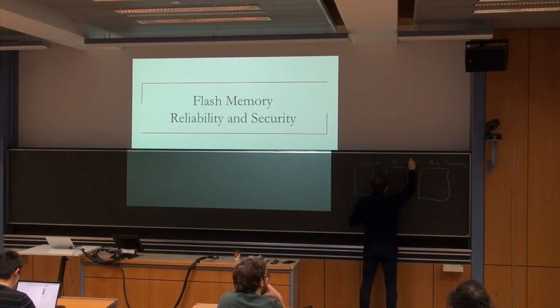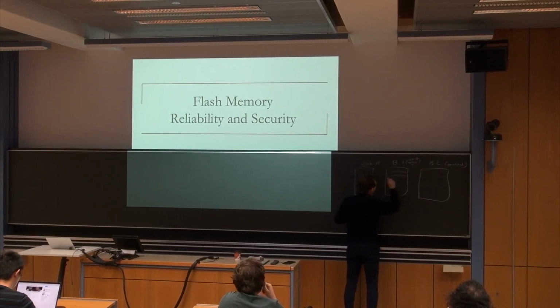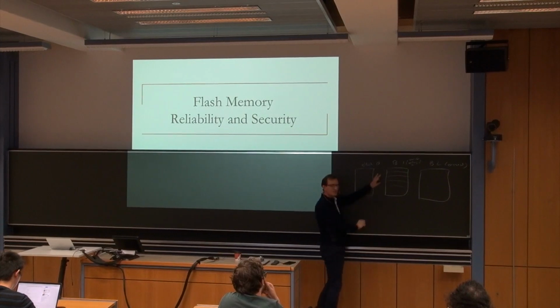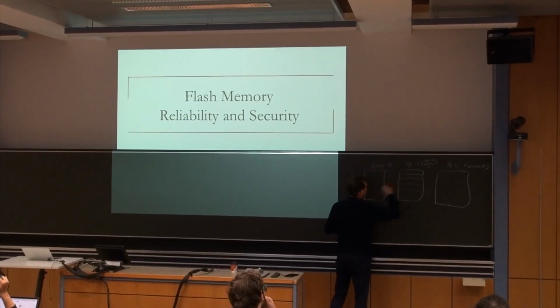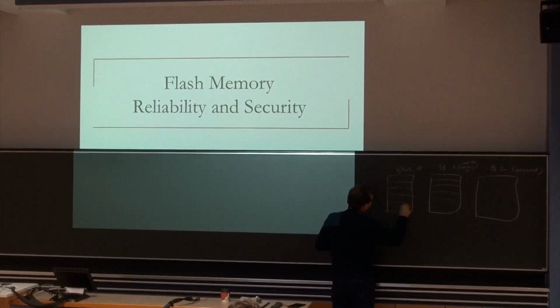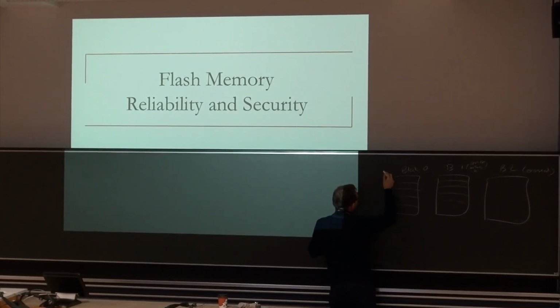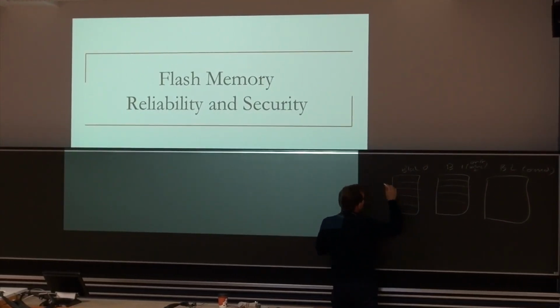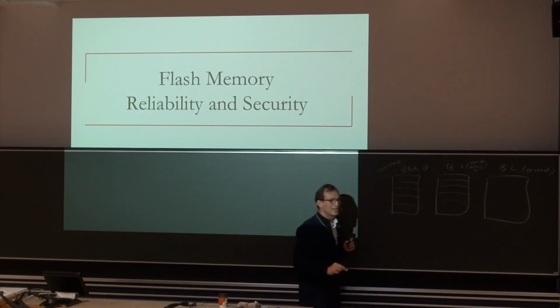So open for writing, I'll call it. Meaning some of them are erased and some of them are being written to, because you've just erased it and you're directing your writes over here. And this is a block that, let's assume, is not erased, it's not open for writing, it's populated. So these are 3 different types of blocks.